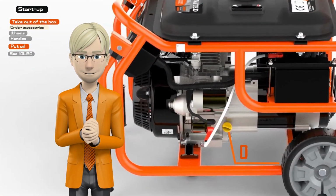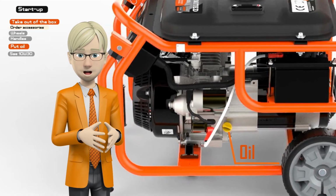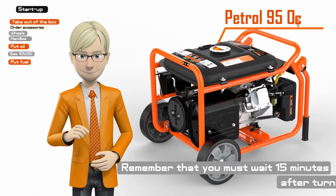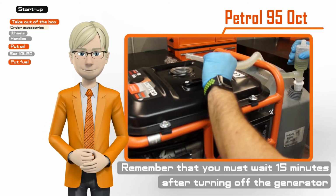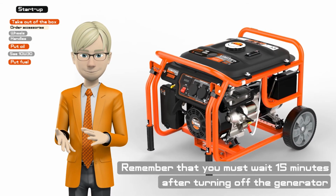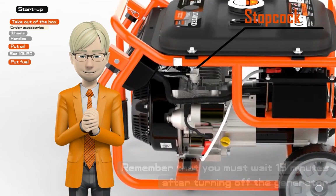Once the oil is in, we will put the fuel, 95 octane gasoline, in and pour it through the inlet filter to avoid rubbish from entering the tank. Remember to wait 15 minutes after turning off the generator before refueling. It should never be done with the generator running. Once the equipment is refueled, we will open the gasoline stopcock to the engine.